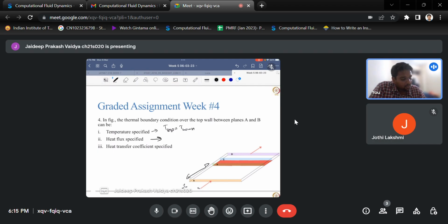The second way is to provide heat or take away heat, or by cooling it. That can be done by specifying the heat flux, whether we can provide adiabatic condition for perfect insulation if the reactant is entering at the given condition, or you can say that it can be heated up, dT by dx, dT by dy can be given, h A delta T, something like that, by providing an appropriate heat flux over there. Yeah, it can be some function of temperature over here.